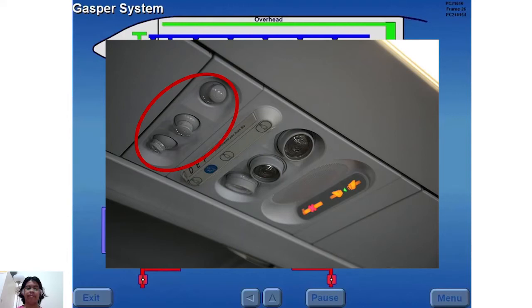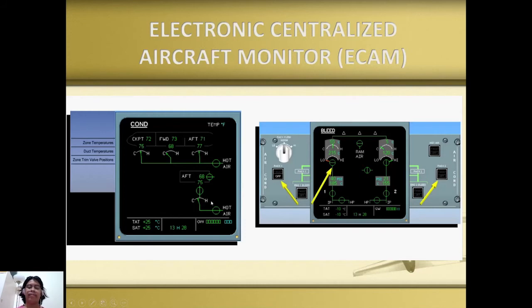All these systems are monitored and the respective statuses are relayed to the flight crew through the monitoring devices, namely Electronic Centralized Aircraft Monitoring or ECAM for Airbus and Engine Indicating Crew Alerting System or EICAS for Boeing aircraft. This monitoring apparatus applies to all aircraft systems in operation. For these topics, there are instruments here to indicate the status of the air circulation as well as the cabin pressurization.